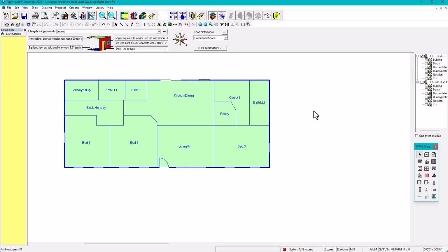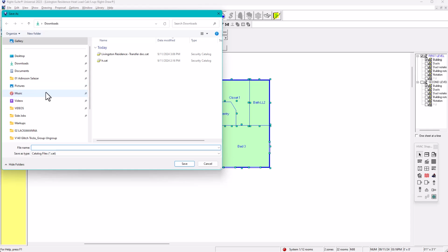So there's always glitches in Wrightsoft. Not always. I mean, in case there is a glitch in Wrightsoft, it happens. It doesn't mean that it doesn't happen. What you do is, let's try with not grouping. So with no grouping, you're gonna go Control-C, new catalog, right click, paste. There you go. And now you have to save this somewhere because it's a new catalog.